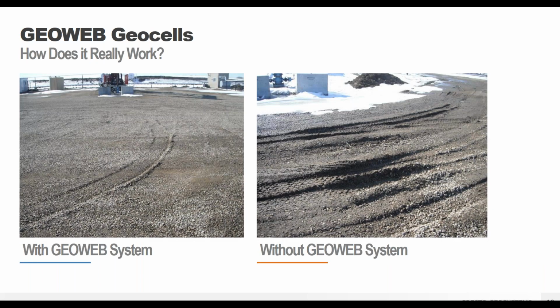And finally, everybody always asks, does this actually work? You know, you put all this information out there, but what am I actually seeing? And so you can see a real difference in the same container yard. On the right side is the before picture without the GeoWeb system, and then the left with the GeoWeb system. And so this was with a fully loaded transport truck. So again, that HS25 loading.